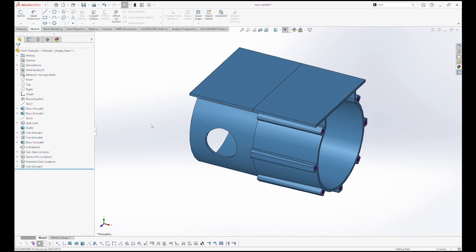It increases the cost of the tooling. It's something that we do on a day in, day out basis. We do a lot of optical parts, but it does increase the lead time and the tooling cost. But if you need a perfect mirrored finish in a very specific shape and or formula, there are finishes that can be done for the core pins and or the cavity surfaces that are available in that specialized finishes category.